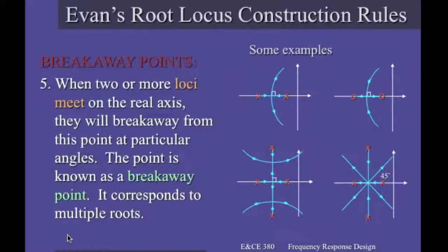There is a special point on the real axis from which 2 or more trajectories intersect and after that leave the real axis, like here, or vice versa, 2 or more trajectories intersect when coming from the upper and the lower half plane, and after such an intersection conflict, they move on the real axis.